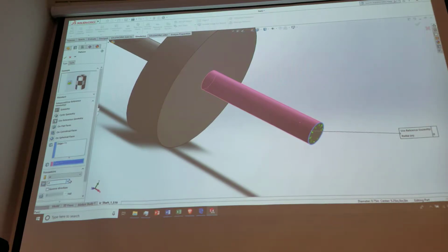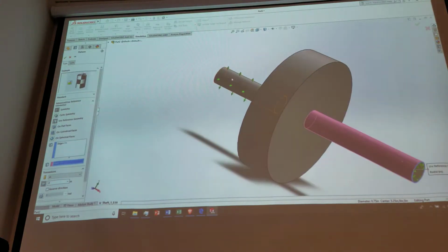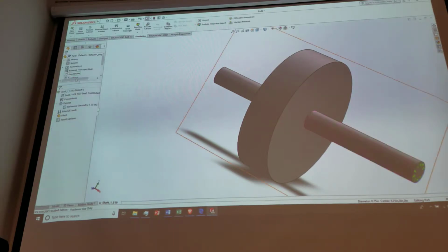That's the equivalent of this, right? Because all it's doing is supporting it this way, and this way, actually, because it's the radial, right here all the way around. It's not supporting it from going in and out this way. That would be the axial direction. It's also not preventing it from twisting, which I certainly don't want it to do because I'm gonna have to put a torque on this end. Right? Okay? So that's not a bad one. Let's just try this. And then let's go over to the other end. Okay, I'm happy with that, so I'll say that one.